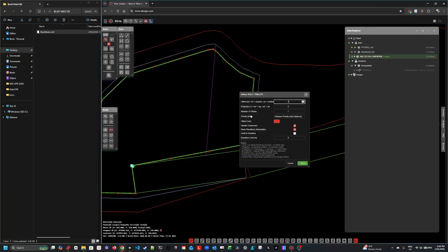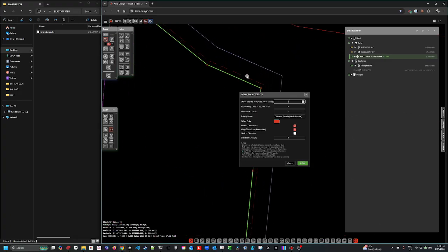Now that we've got it, you can see in here there's a dashed line. We just changed that to what we want to offset it as, and maybe we've got a protection area of, I don't know, 0.3. They're only very small holes, 115, so yeah, 0.3. That will give us a couple of 175 mil off the wall, right here.